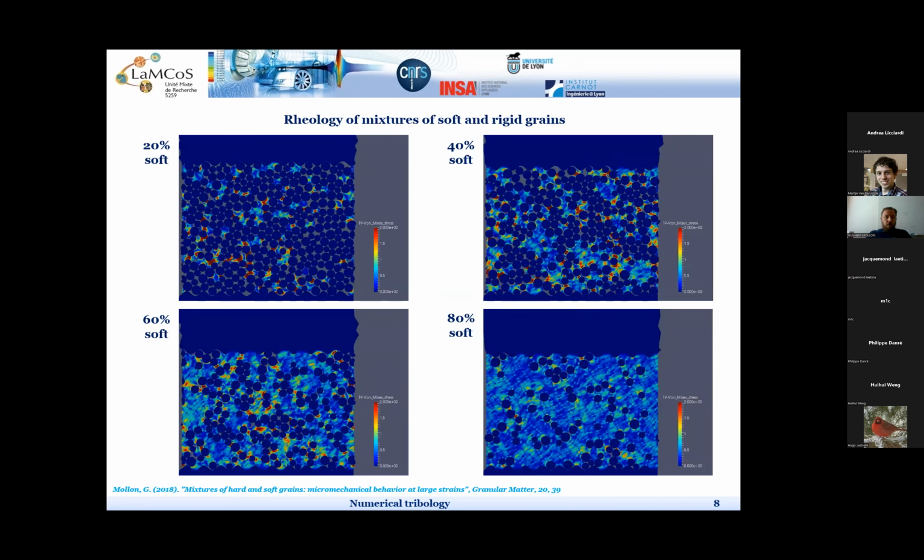We've been applying this as well to the abrasive wear of diamond tools during rock cutting or during concrete cutting. And for example, you see that in this case, we're abrading some surface by some granular flow. And by zooming in, we can see that we can represent the stress concentration at the contact, the emission of acoustic waves inside the medium, and the abrasive wear with the separation of matter from the surface, and this matter then gets entrained into the granular flow.